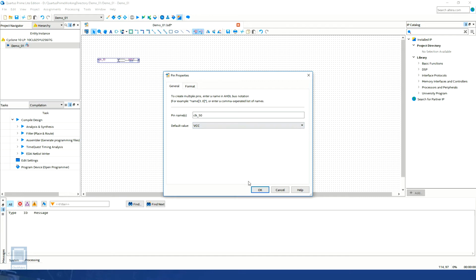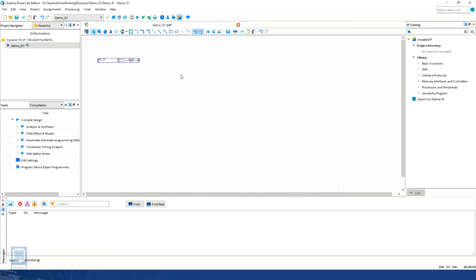Now let's add the output pins, or LEDs, to our design. Let's use the Add Pin tool this time. We will need 4 output pins for this design. Since the schematic editor is granulated, we can actually use the granules to properly space our components. Now let's assign some names to these LEDs. The schematic editor makes it really easy to name similar components in a sequence by hopping from one component to another like this. Now we are done with the input and output pins.